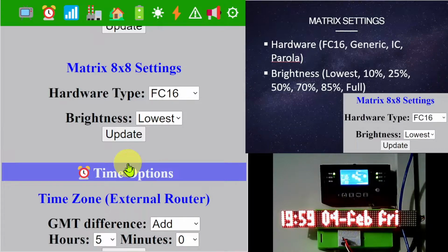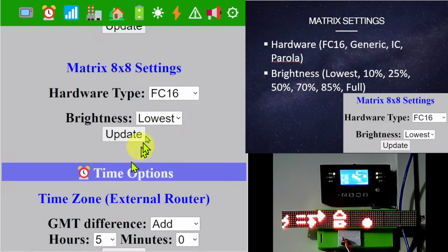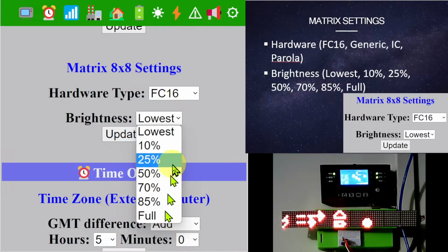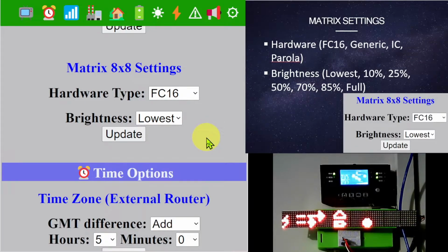Need to go back to lowest settings. Device got stuck. As I mentioned, power is an issue. I am supplying power through the USB connector of the ESP32. Need to supply power through VCC and directly to all modules. Then power issues will be taken care of.